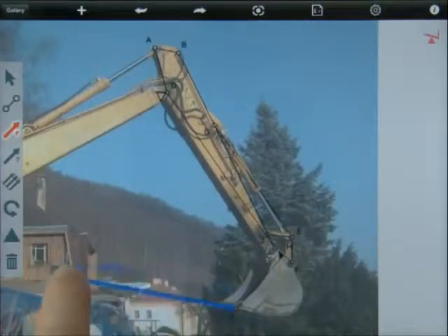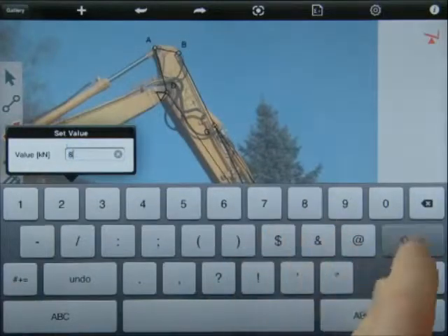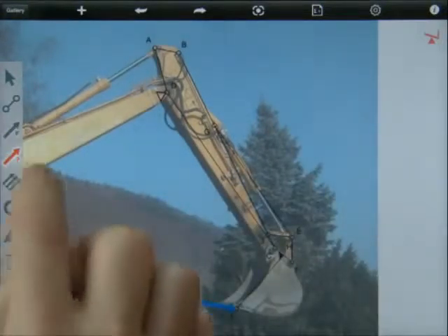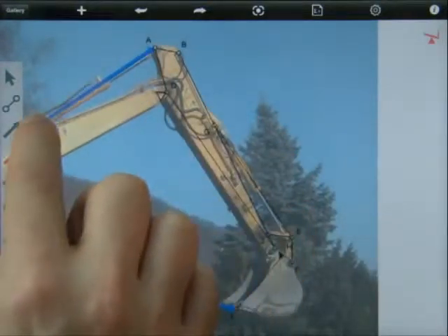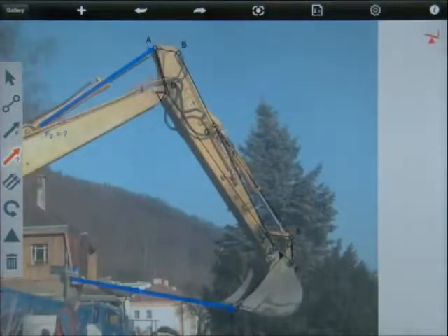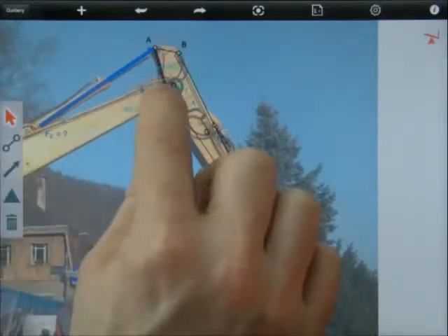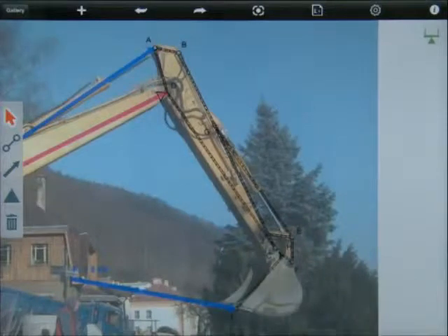A known external force is used for the breakout resistance at the bucket. An unknown force is used at the opposite end of the stick to calculate the resultant force. Segments not included in the force vectors display as single lines. Segments included in the force vectors will display as hashed double lines. For this scenario, a welded pin is added and ForceEffect solves the diagram.